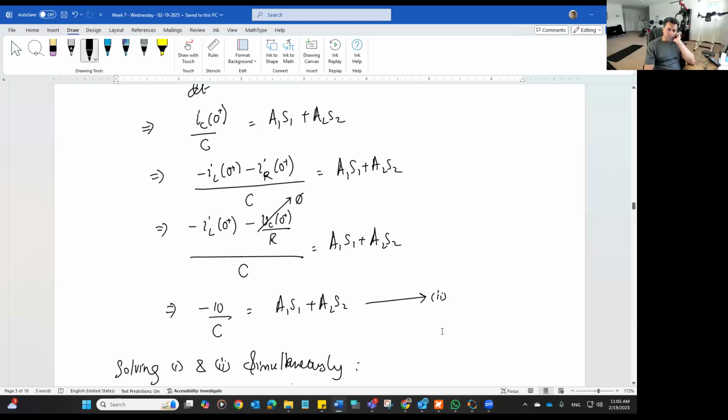Well, guys, any question about this problem? Standard steps, remember, but when you're finding the derivative and then plugging in the current and later the voltages, you have to look at the circuit and decide how you're going to write that equation of IC0 positive in this case, or VC0 positive, IL0 positive, whatever you're putting down. That's coming from the circuit.